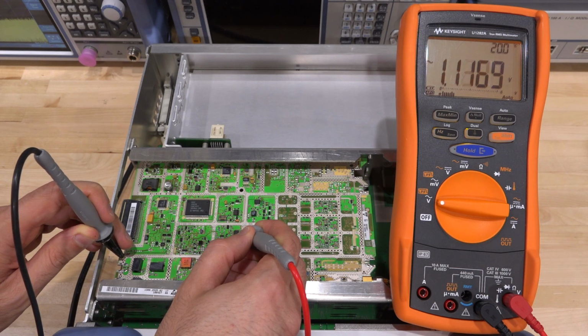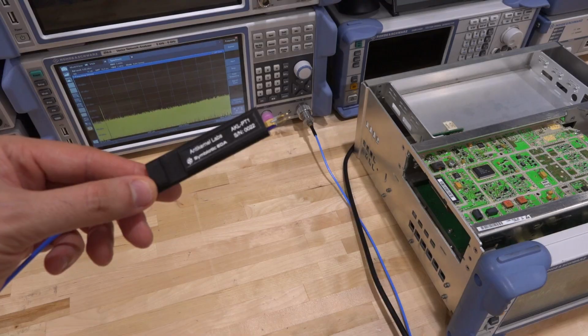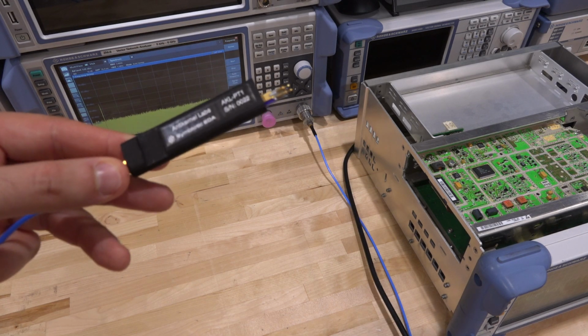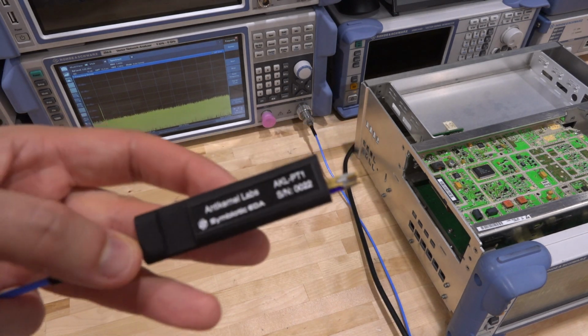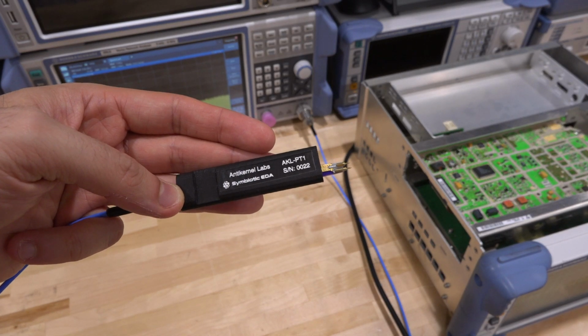There you go, see? There's AC voltage there, and that's because the PLL is trying to lock continuously. So since the VCO has some tune voltage on it, I think it's a good time to take a look at it in the RF domain. In order to snoop on the RF signals without interfering with the signal flow, we're going to use this inexpensive probe, which I reviewed in one of the previous videos as well.